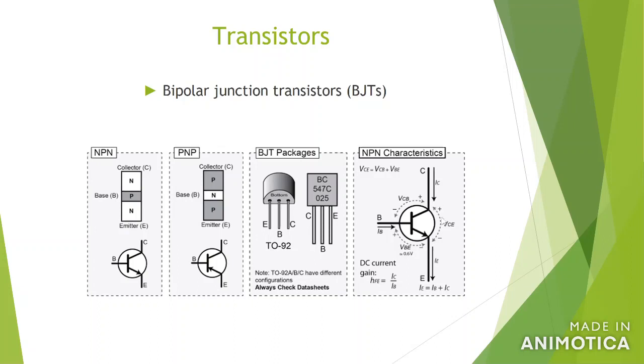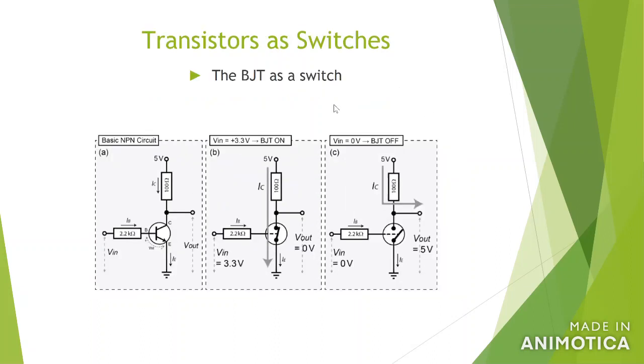So a transistor can help the Raspberry Pi or other microprocessors drive high current devices by only using a small current. The small current from the Raspberry Pi flows into the base, and then the high current will drive a high current device connected to C or E. That's why transistors are so important and so popular in electrical circuits. And in fact, transistors can work as switches.